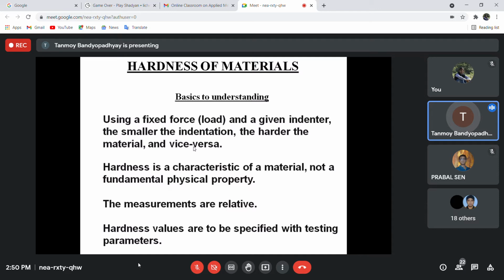At another point of the specimen, if it has a lower carbon percentage, that will have a lesser hardness. So hardness is a property of the material that changes with many things like heat treatment, carbon percentage, and any other additives. Based on many factors during the manufacturing or processing of this specimen, the hardness of the material varies. So at any two different points of this specimen, you can get different hardness for the same material. So it's not an absolute property of the material.